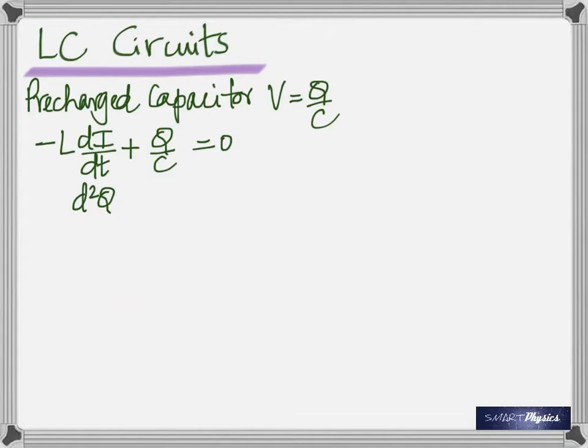Somebody tell me this. When you just connect the capacitor to the coil, what can you say about di by dt? Use the words maximum, minimum. Think practically. You have a completely charged capacitor, you just connected it to a coil. What's the capacitor going to do? Discharge. And now my question is, is it going to discharge at the fastest at that instant? Or is it going to discharge at the slowest at that instant? Is it going to be fast and then get slower? Or is it going to be slow and then get faster? This is actually a common sense question.